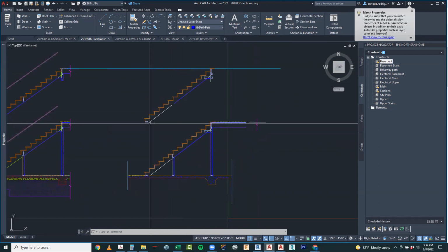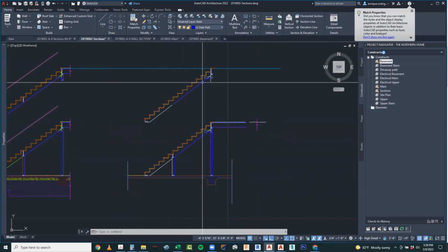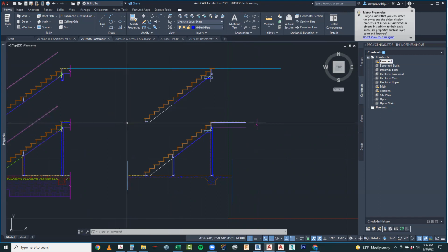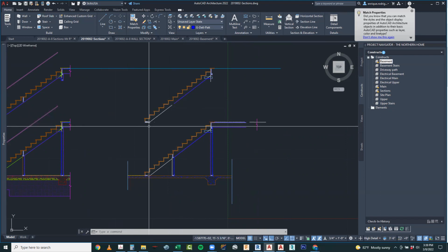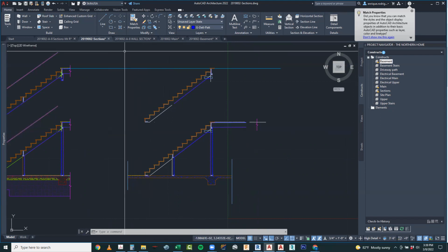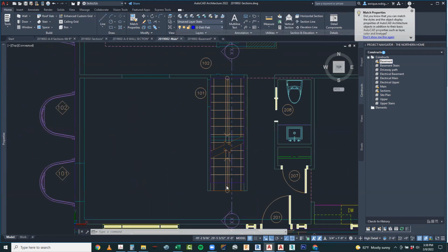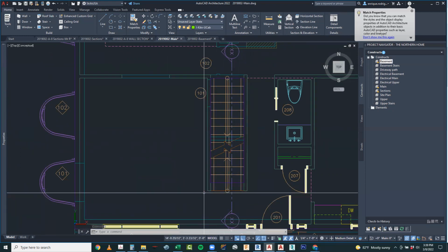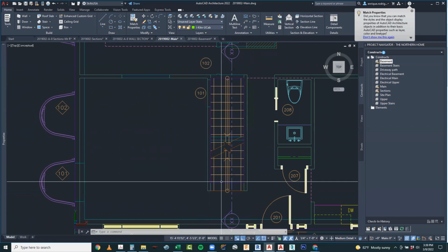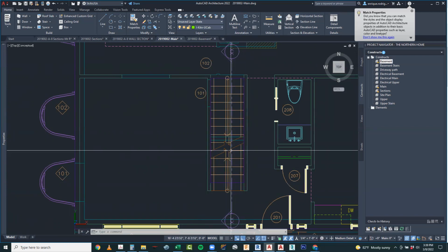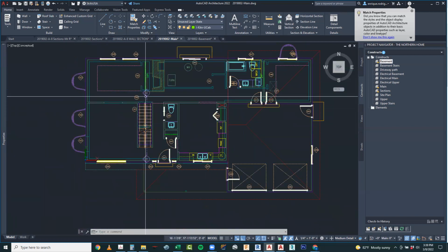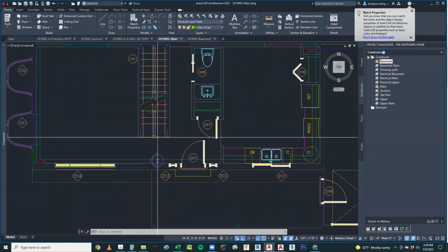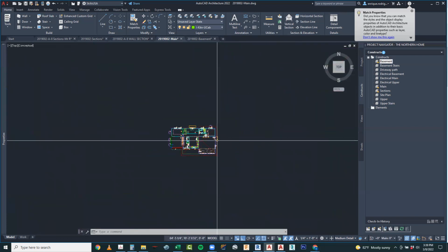Okay. Now, remember, this is basement to main level. Your front door is somewhere over in here. So we're stepping in this way. So there is a floor here, and it actually stops right here. So if you go to your main floor, that floor right here has support members right underneath it to this point, right about this point. And then there's an open hole underneath here, okay? That leads down because the basement stair is coming down this way. So what we need to do is we need to establish our supports for that.